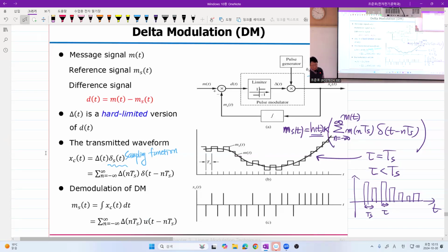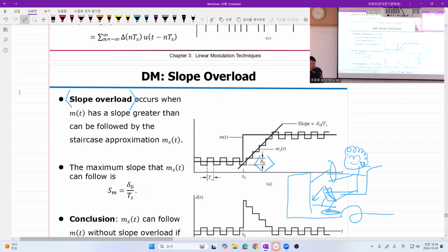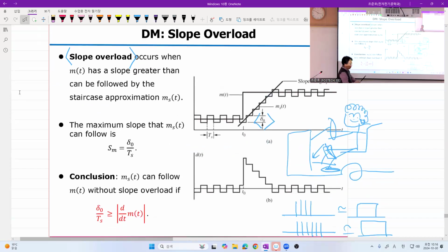The problem of this delta modulation is that if you make an error in demodulation, the error propagates, right? Because the differences will be added and added, so your error will last for a long time. Anyway, people wanted to save the number of digital bits when they converted the analog telephony network to the digital telephone network, and that's what we talk about.